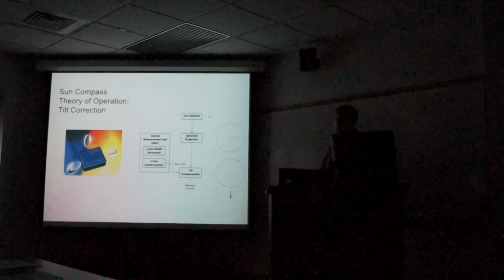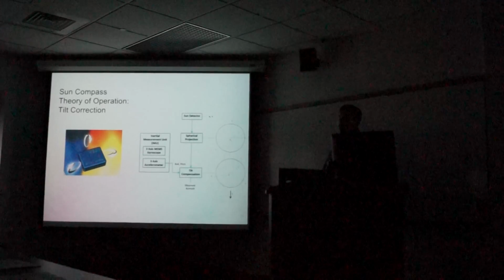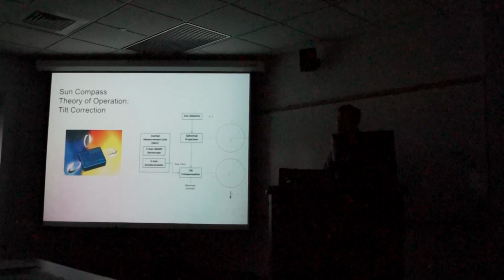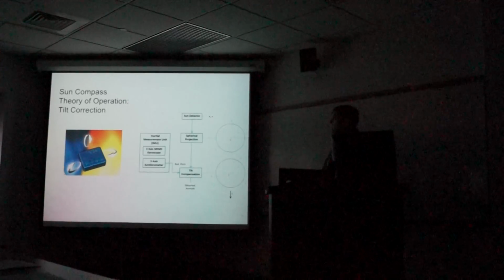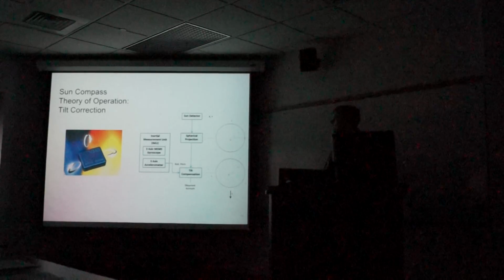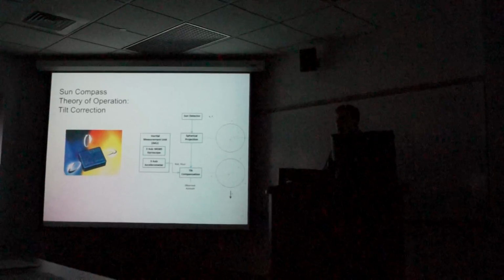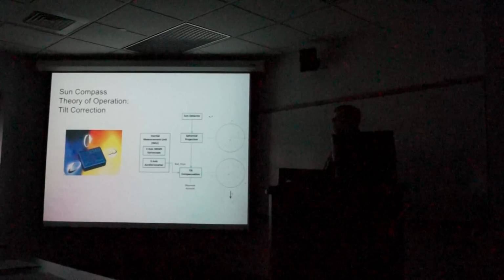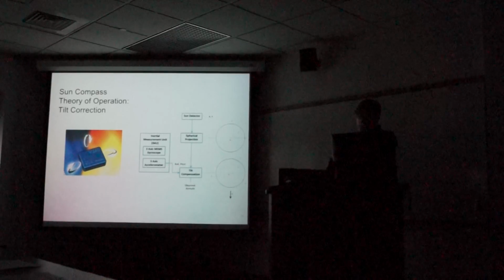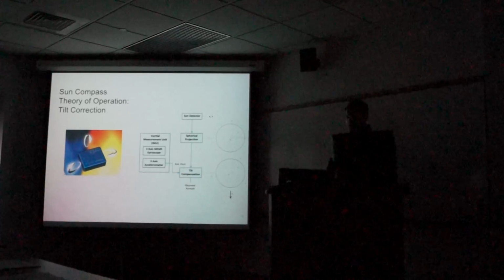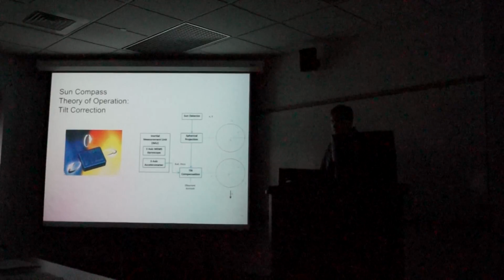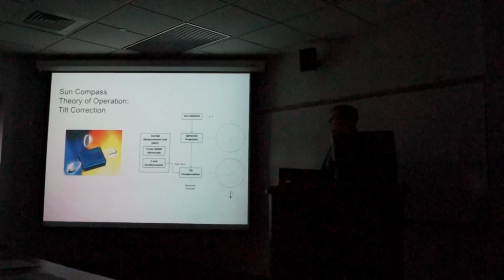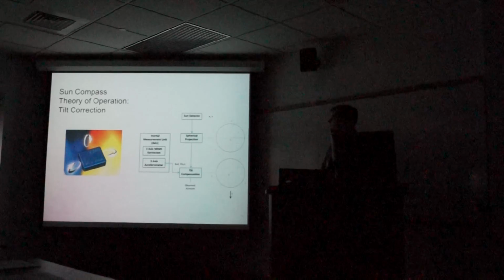Right, so how did you do that fusion? So that was done with a complementary filter, just a simple one. How does that work? It does a weighted combination of the accelerometer and gyroscope values over time. There's a little bit of a tuning parameter. I think it was 0.98 or 0.098 for the accelerometer, to more heavily weight the accelerometer values to help curtail the drift from the gyroscope measurements.